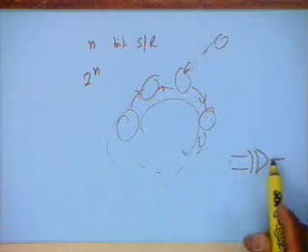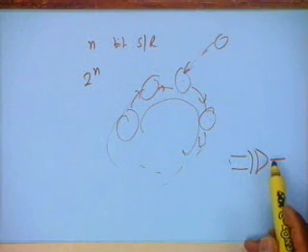If you choose any other gate, it will essentially not give you this behavior, because out of the 4 possible inputs, for 2 inputs the output is 0, and for the 2 inputs the output is 1. So you choose an exclusive OR gate for generating the feedback. Whatever value that you start from here is called the seed.